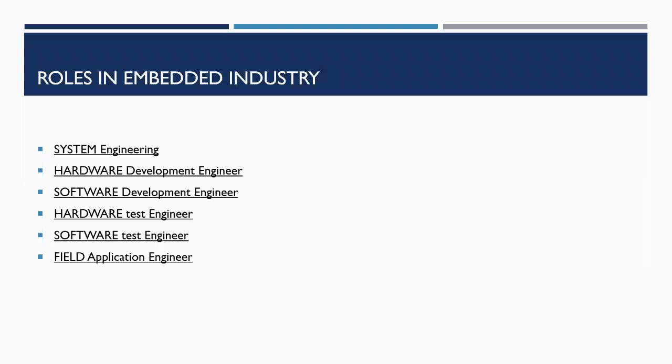Once they are very good at developing circuits on a breadboard, next they have to take general purpose PCBs. On this general purpose PCB, they have to place the electronic components as per their circuit diagram, then solder them, and then carry out their experiments.